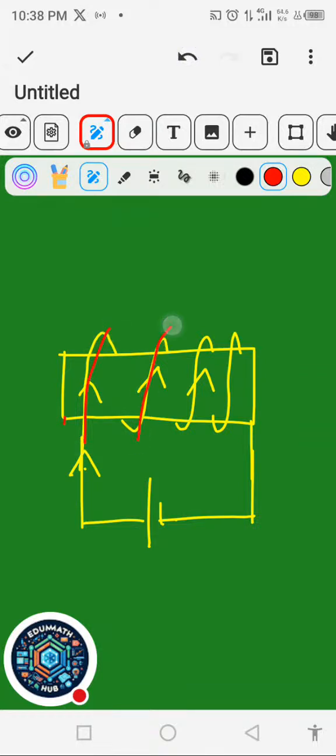These coils of wire that you are looking at, that's a solenoid. So you put this steel bar into the coil of wire, then you apply direct current. Take note, they can ask you in exam which current is used. It is direct current, not AC. To magnetize this bar, you use DC. So you apply DC for some minutes.